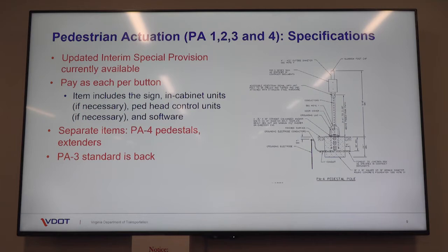And so designers, when they lay out accessible pedestrian signal push buttons, should ensure that the face of the push button is within 10 inches of accessible distance. And that's for new signals. For modifications, they need to be to the maximum extent feasible, but still within 2 feet reach.